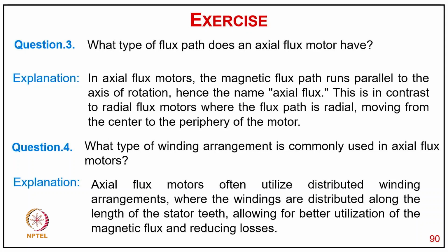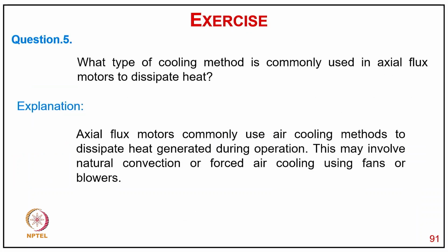Question 4: what type of winding arrangement is commonly used in axial flux machines? Explanation: axial flux motors often utilize a distributed winding arrangement, where the windings are distributed along the length of the stator teeth, allowing better utilization of magnetic flux and reducing losses.